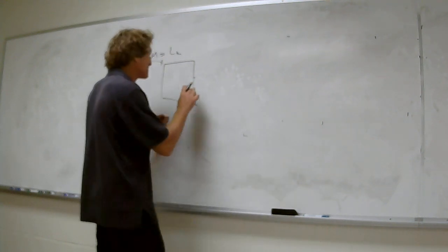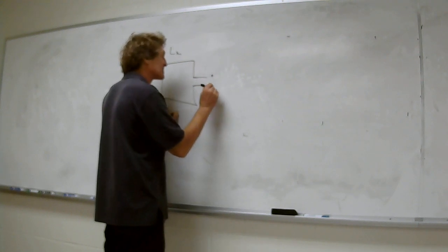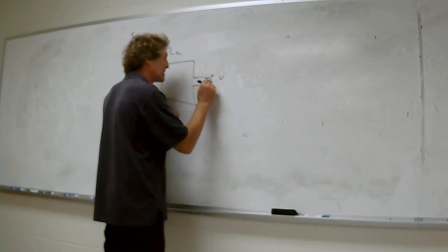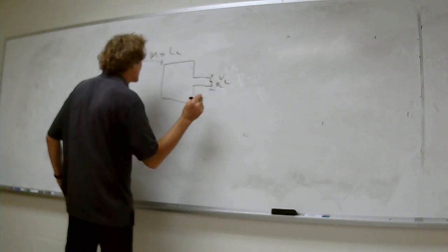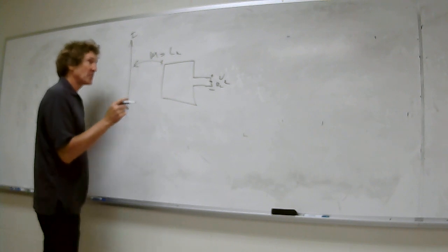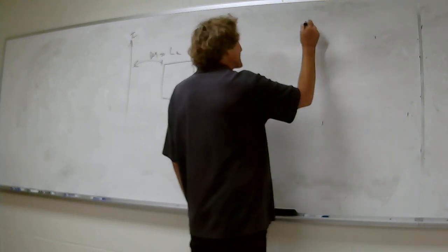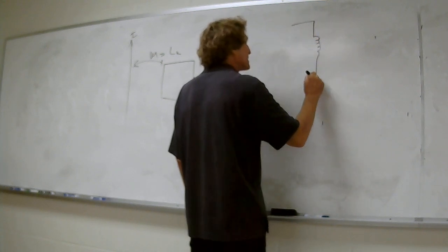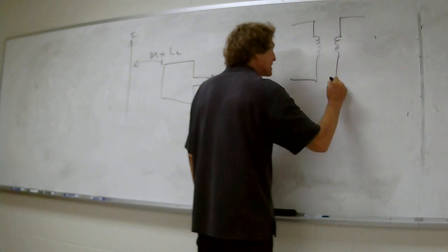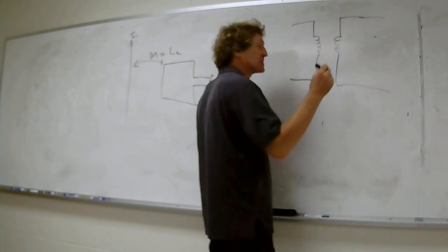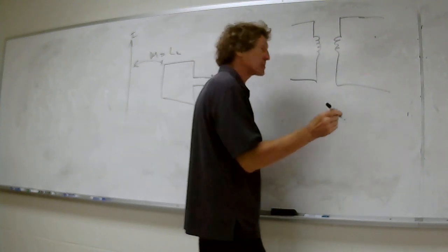Well, technically, mutual inductance means this. If you have a gap here, plus to minus V, and I'm going to put a load here, R load, here, I'll call this V2, and you take a look at mutual inductance and self-inductance. Let me do it with a magnetic circuit, the way they do it. You'll appreciate this more. So normally they do this. Now, this looks like a transformer if it had turns ratios, but technically this is a magnetically coupled circuit symbol.